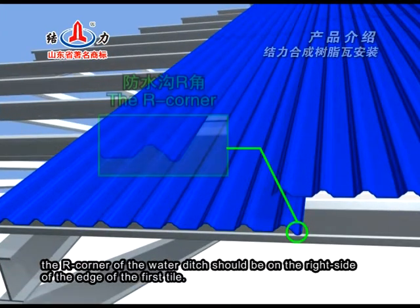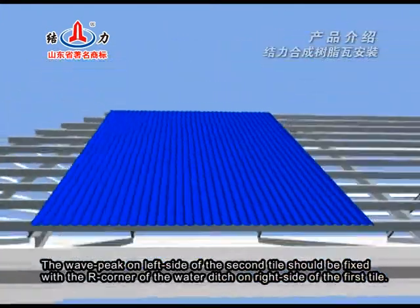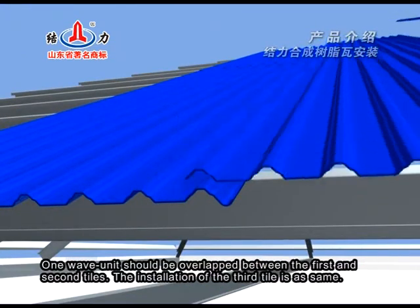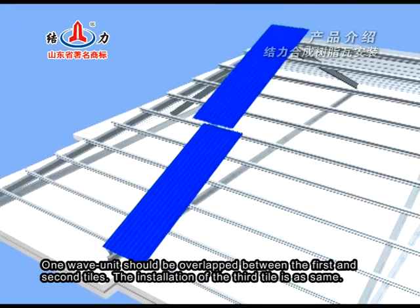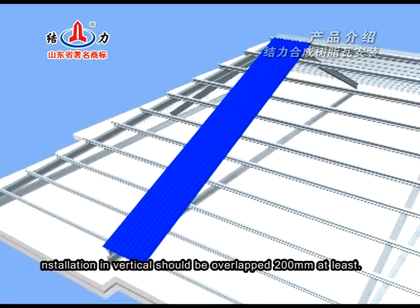The arc corner of the water ditch should be on the right side of the edge of the first tile. The wave peak on left side of the second tile should be fixed with the arc corner of the water ditch on right side of the first tile. One wave unit shall be overlapped between the first and second tiles. The installation of the third tile is the same. Installation in vertical direction should be overlapped 200 mm at least.